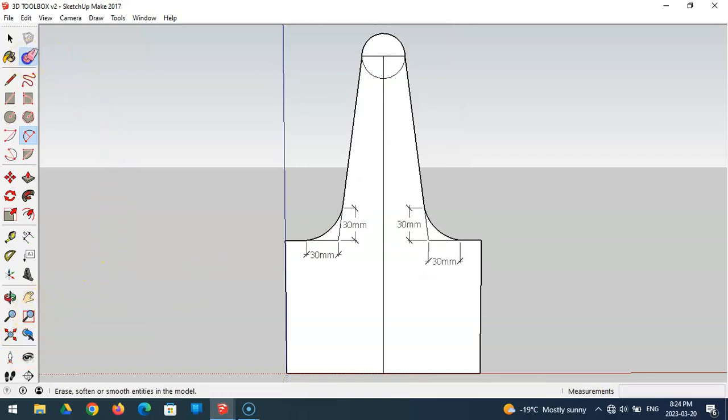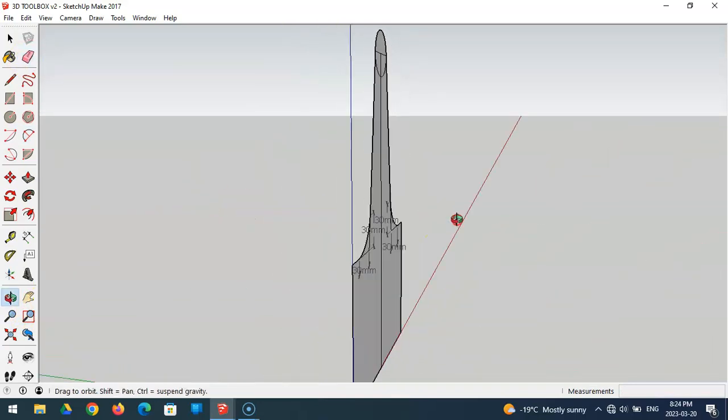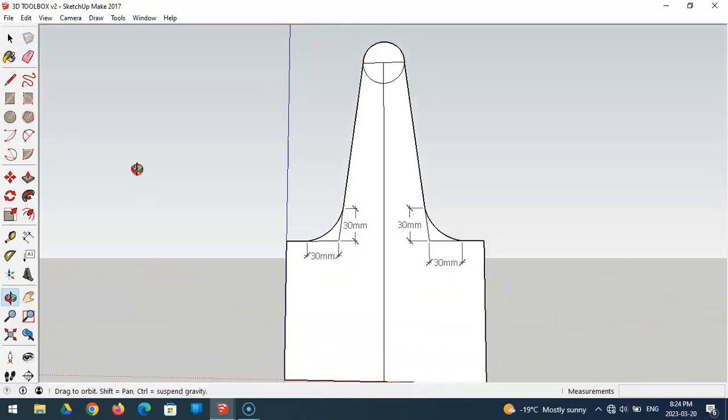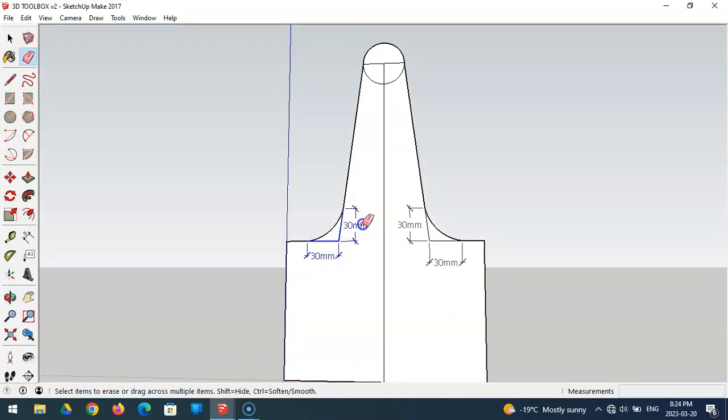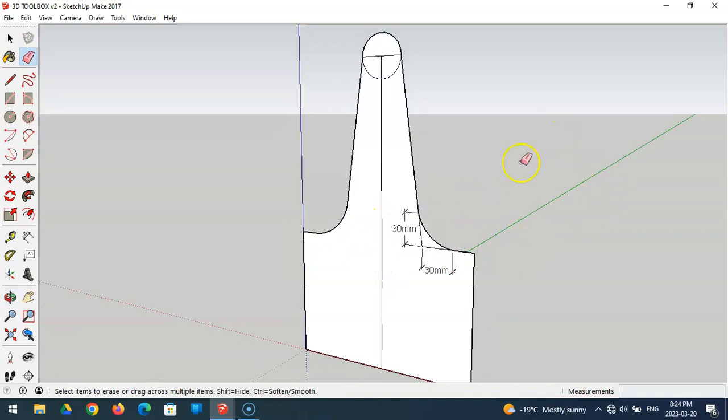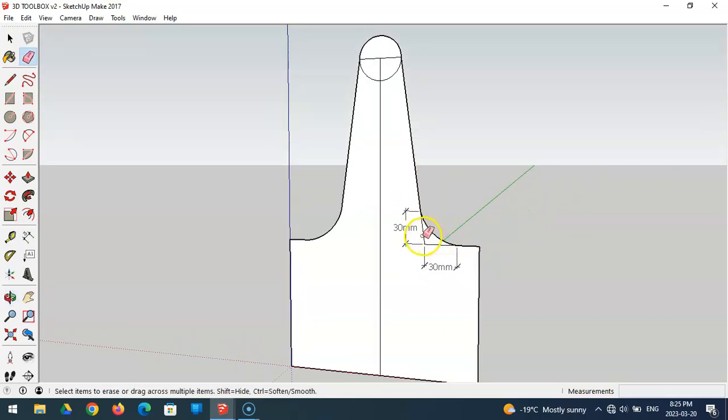So this is the eraser tool. When I have nothing behind here, this is a flat piece of paper, I can drag the eraser tool like this. If I have things behind here, if this is a 3D object behind here, I don't want to drag it because it will sometimes erase the pieces behind here that I can't see. Then I would just single click. And then it will only erase one item at a time.